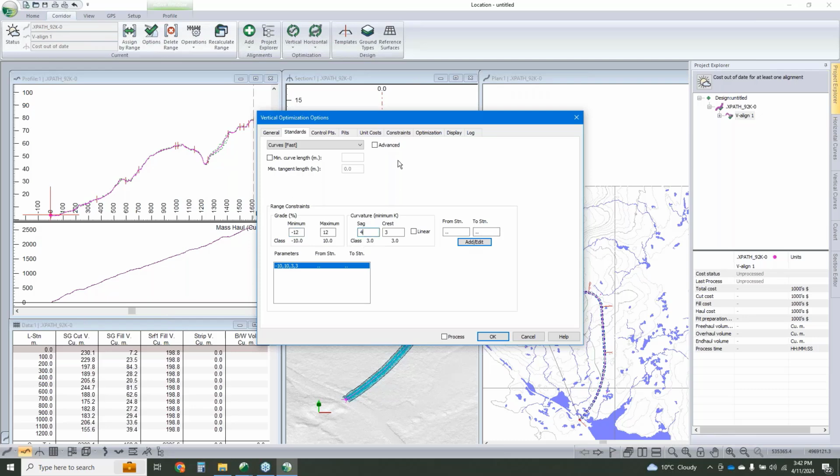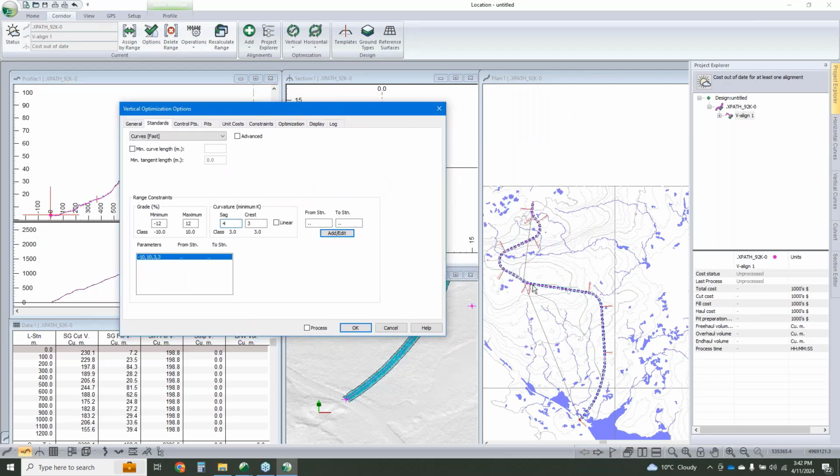And here I will mention this example that I'm showing. I'm kind of doing it off the cuff as a wind farm example, but we can be much more complete at the expense of a couple extra minutes here. So we could include the actual pads next to our turbine locations with crane laydowns, all in our earthworks. And with that, I'd probably reduce my grades at those sites as well too. So we don't have crane laydown on 12% grade, for example.